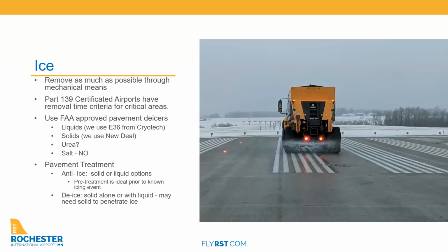You put it in with a forklift. Most people probably have a sanding truck that they can use. If they use one in the city, you can wash it out, get the salt out of it, wash it out real good, and then apply the solid. And if you're not there when it rains and you get a 1/4 inch of ice, you could still apply that solid. It'll go down through the ice and break it up.